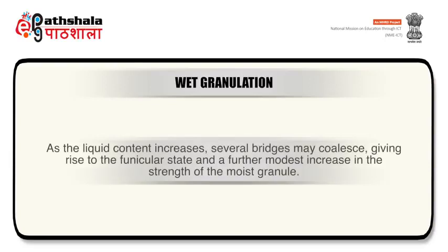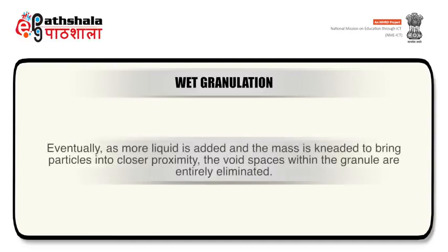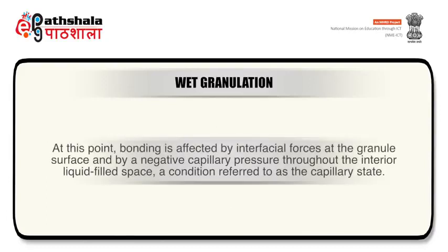As the liquid content increases, several bridges may coalesce, giving rise to the funicular state and a further modest increase in the strength of the moist granule. Eventually, as more liquid is added and the mass is kneaded, this brings particles into close proximity. The void spaces between the granules are entirely eliminated. At this point, bonding is affected by interfacial forces at the granular surface and by a negative capillary pressure throughout the interior liquid-filled space, a condition referred to as the capillary state.